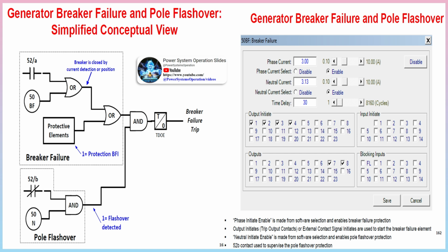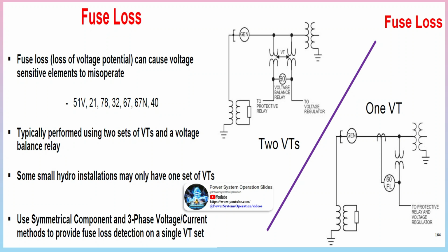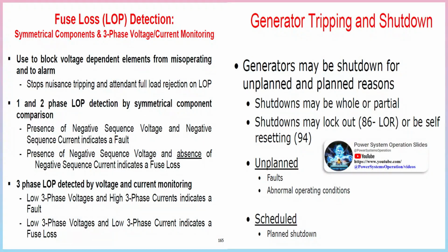Protection against rotor distortion. The cooling rates following shutdown, at the top and bottom of the turbine casing, are different, and this uneven temperature distribution tends to cause distortion of the rotor. To minimize the distortion, it is common practice to turn the rotor at low speed during the cooling down period. In view of the forces involved with large modern rotors, it is now standard practice to fit shaft eccentricity detectors.